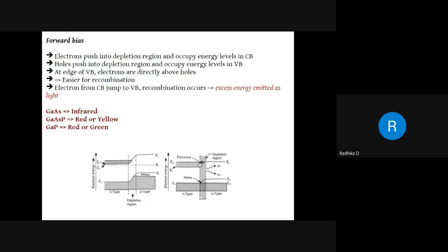You will get more electrons in the conduction band and more holes in the valence band. Is that clear? Is that acceptable? By default, you have more free electrons in the conduction band and more holes in the valence band. As for the Fermi level in a PN junction, I'll come to it later, Abhishek. It becomes more complicated, so I will not come to the Fermi level now.